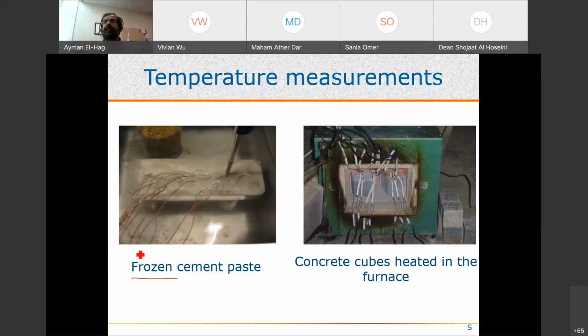Here, the temperature sensors, the most famous ones, either directly change the temperature into a voltage or into a change in resistance. Like the strain gauge, when stress and strain change into a change in resistance, we have to use a Wheatstone bridge to convert that into a change in voltage. At the end of the day, we want the physical change converted into a change in voltage. But one of these sensors, the thermocouple, can do that directly.